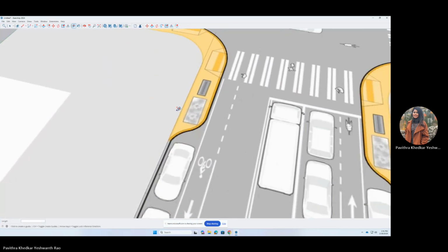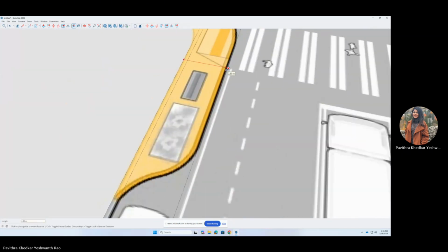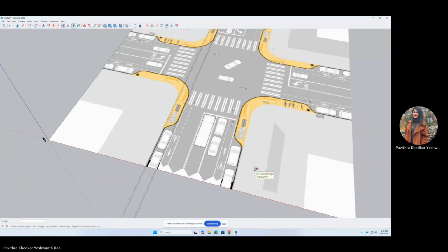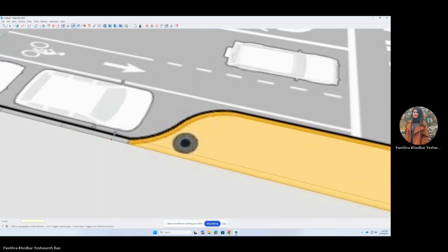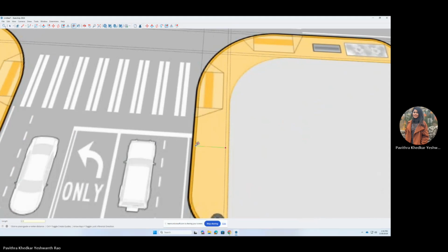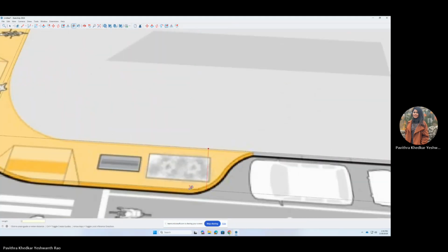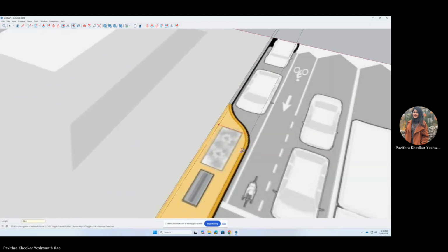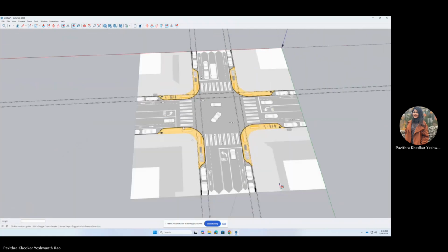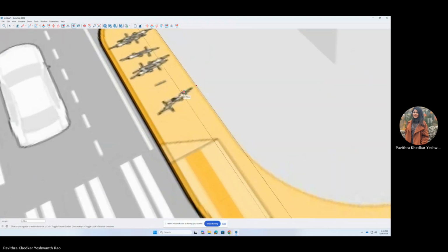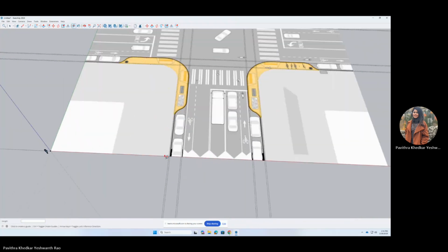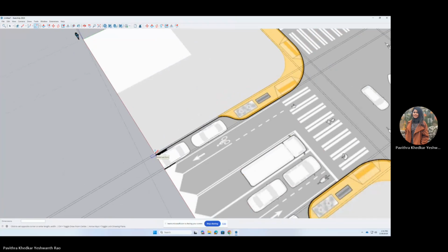Creating reference guidelines for accurate tracing. Use the tape measure tool to draw reference lines on the imported image. Ensure the guidelines follow real-world dimensions rather than relying solely on the image, as pixel distortions can mislead measurements. Maintain consistent spacing between guidelines to ensure accuracy in the curb width, pedestrian path, and street dimensions. Always cross-check dimensions with your city's design references and guidelines for accuracy.